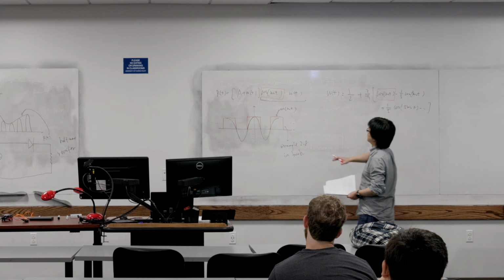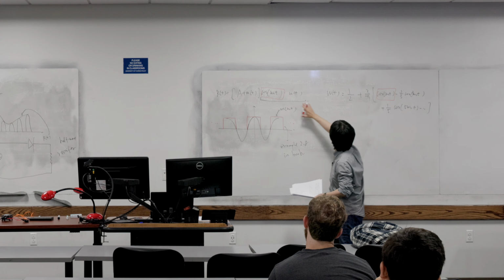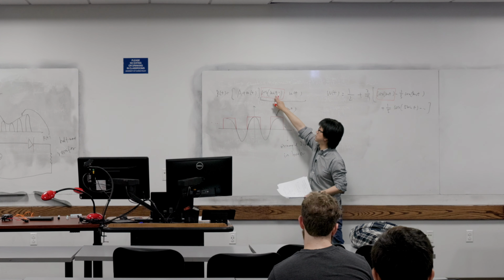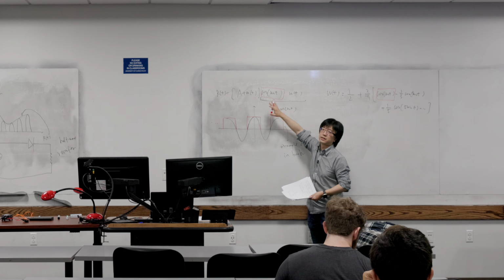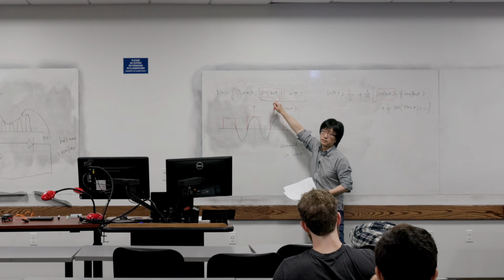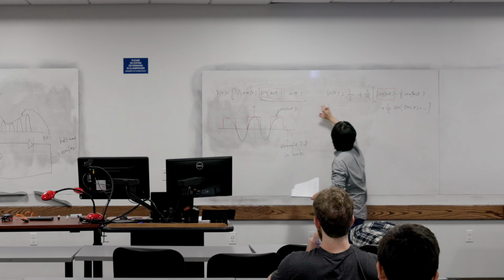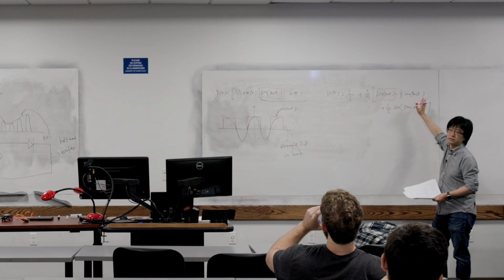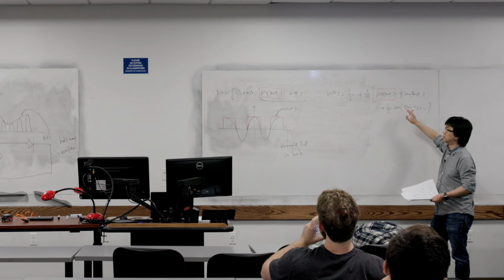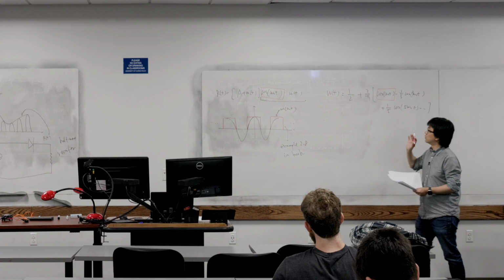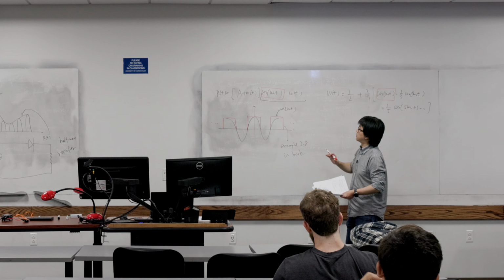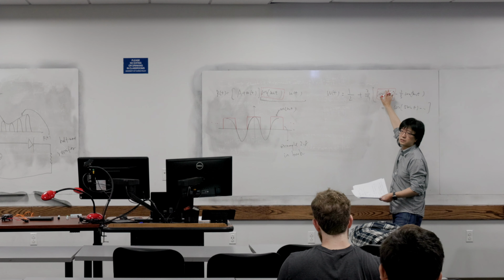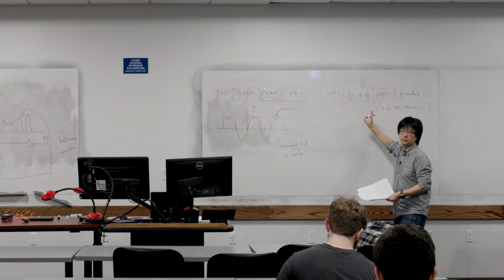The first part, multiplied by the constant, will still be at the frequency of omega_c, which is a higher frequency component. And if we use this part multiplied by the rest of it, it's all high frequency component. So the only low frequency component that we're going to have is this cosine multiplied by that. Everything else will be high frequency component.